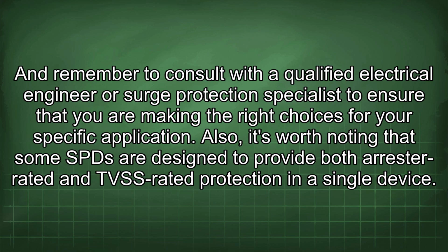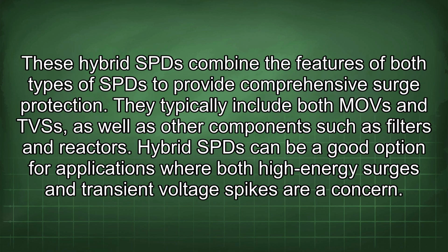And remember to consult with a qualified electrical engineer or surge protection specialist to ensure that you are making the right choices for your specific application. Also, it's worth noting that some SPD are designed to provide both Arrestor-rated and TVSS-rated protection in a single device. These hybrid SPD combine the features of both types of SPD to provide comprehensive surge protection. They typically include both MOV and TVS, as well as other components such as filters and reactors.